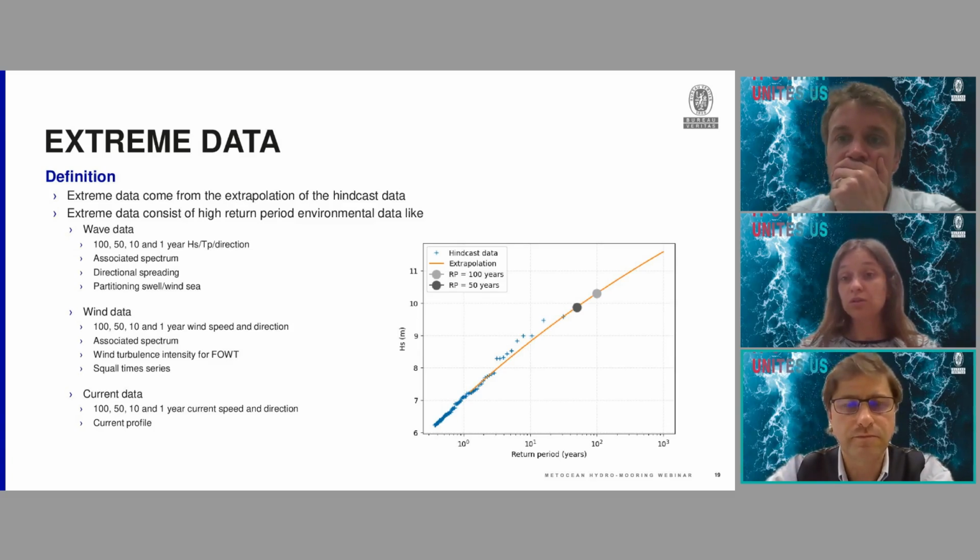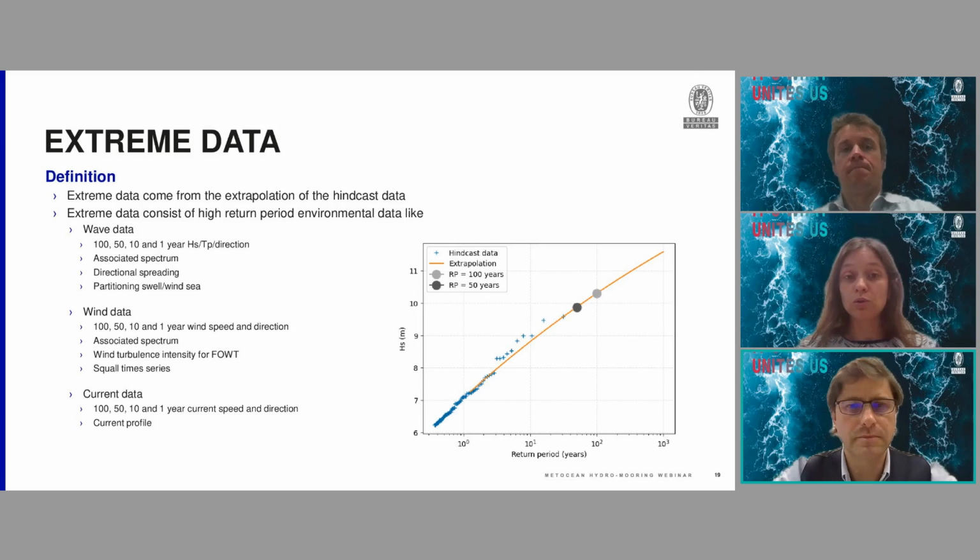If you are doing a hydrodynamic analysis, you might want to not extrapolate the Meteocean data, but extrapolate the results. In that case, you will perform a long-term analysis, spectral analysis for the hydrodynamic. You will have the answers for each point of your scatter diagram, and you will do this extrapolation on the answer and find your 5 years response.